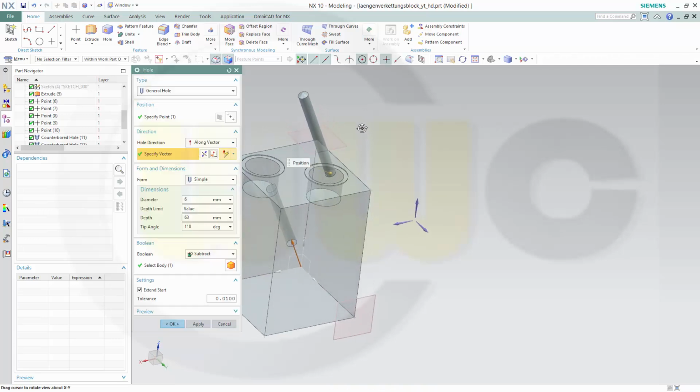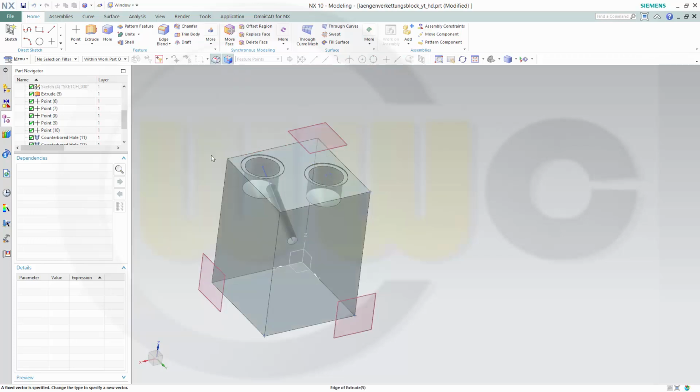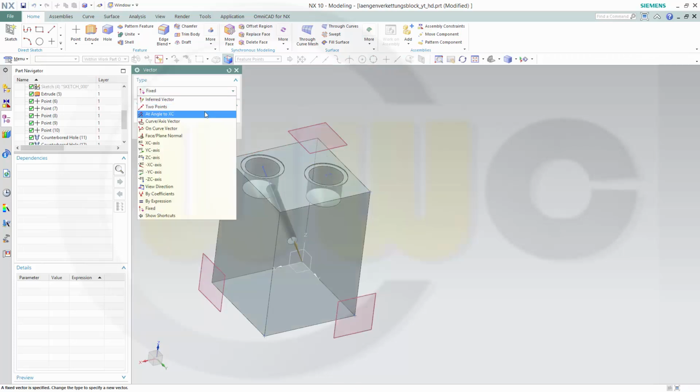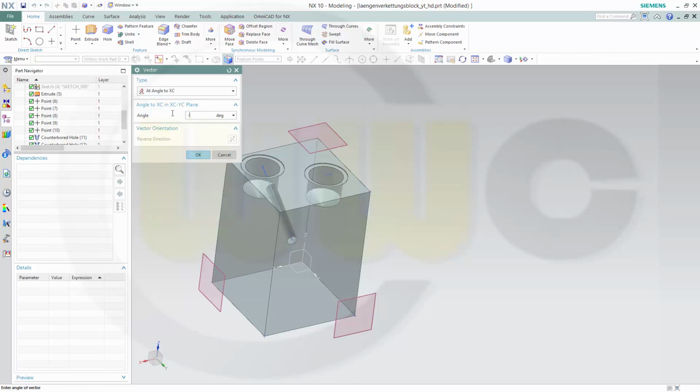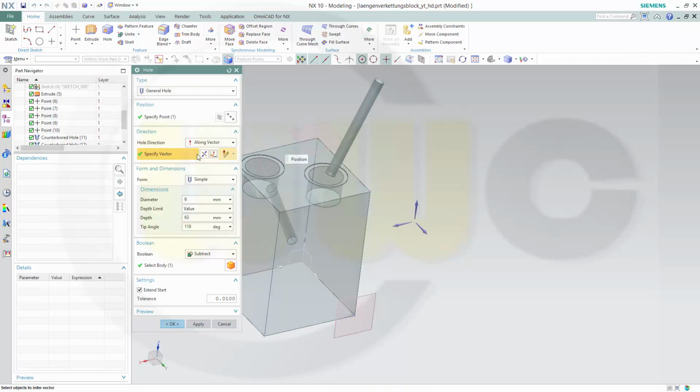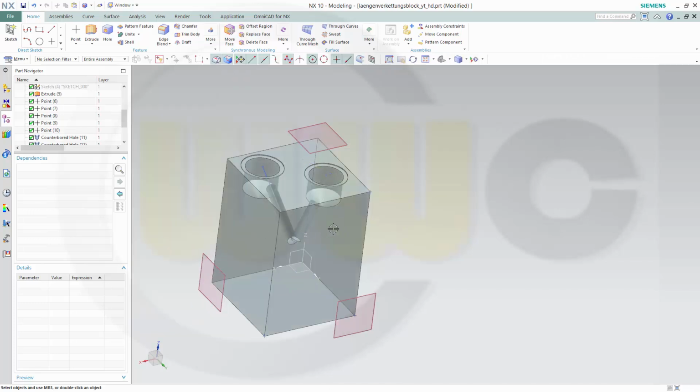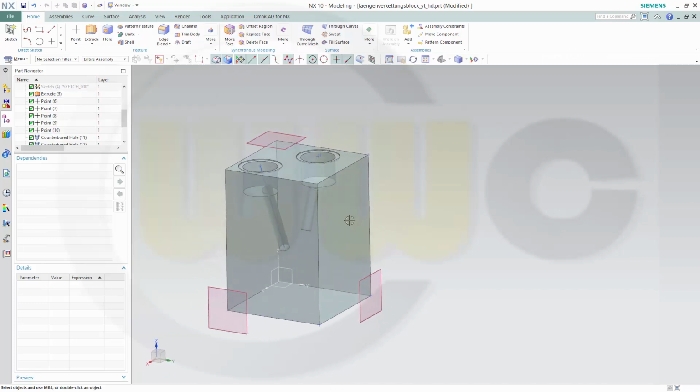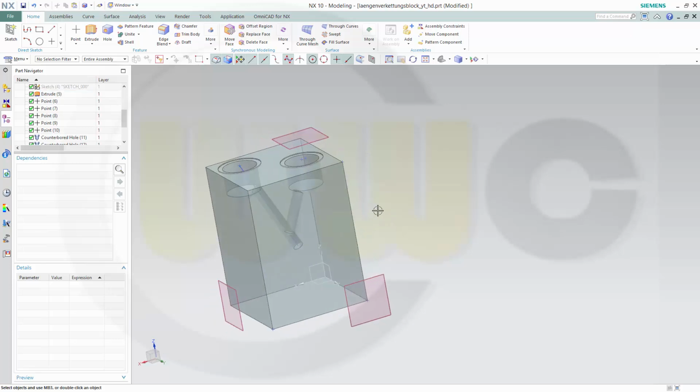So that's the wrong direction. So I will change this one to minus 24. Okay, and now change direction, and the depth should be 44 and confirm. So I didn't need a plane. By repositioning my working coordinate system, I could use the different command in the constructor.